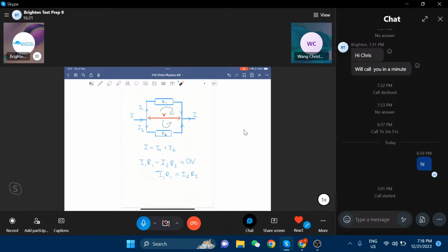That we say this one minus the EMF is equal to this one when we rearrange it, right? In that case, I just make it briefly in orange. So we could say I is equal to this one. Let's assume it's now a 2 volt different situation. It would be 2 volts plus the I2R2, or we say it's I1R1 minus the 2 volts is equal to the I2R2.